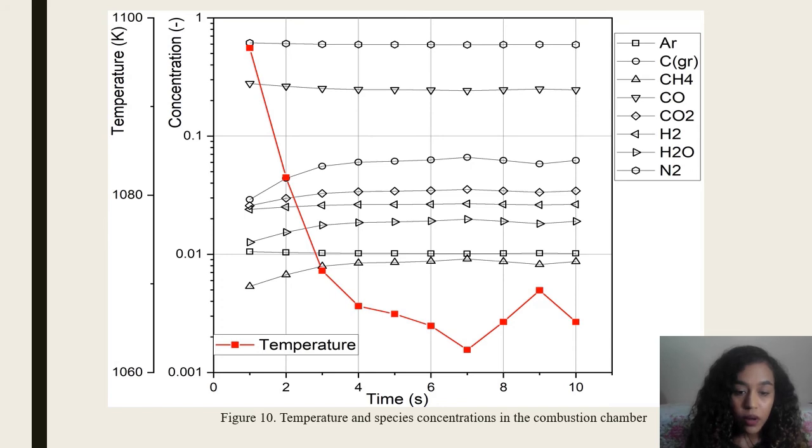As expected, the airborne nitrogen has a maximum mass concentration in the mixture of 59%. Due to the fuel-rich combustion, the second component, carbon monoxide, is 25%. The concentrations of other species are negligible, at most 6.2%. However, they play an essential role in the chain reactions of hydrocarbon fuel.